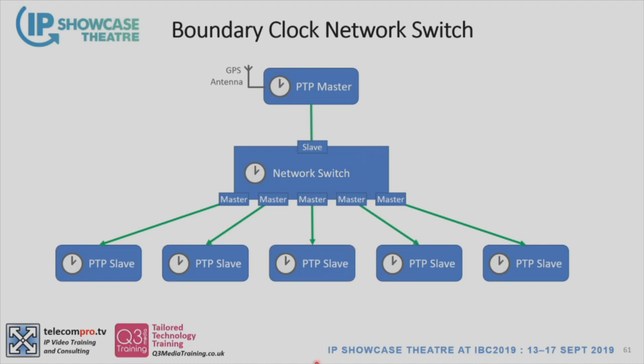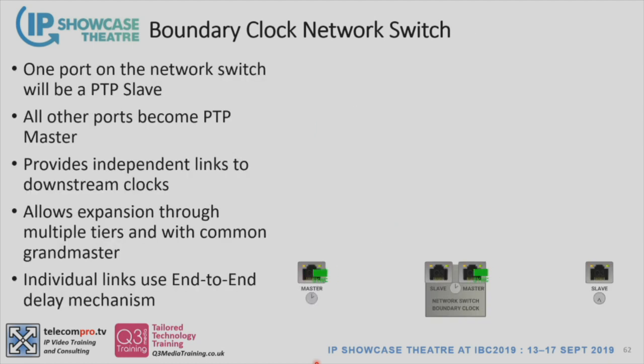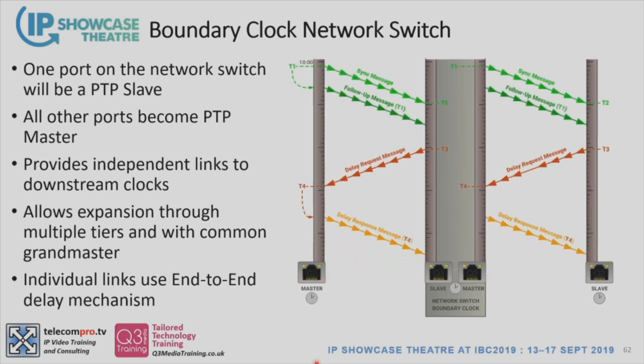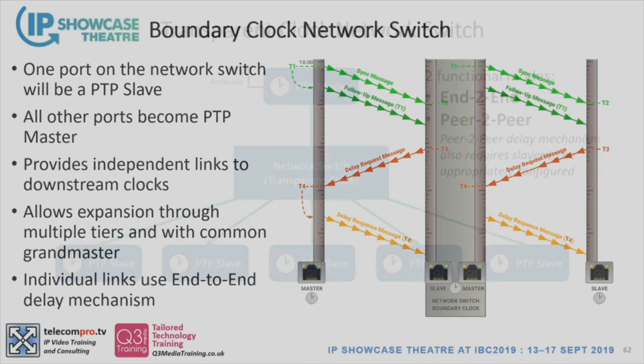Internally on the switch is some code, in either software or hardware, that's implementing PTP ordinary clock mechanisms on each of those ports. So how would that look? Drawing it, I've shown them very synchronous here. In reality, they probably wouldn't be quite so nicely aligned, but there are two independent discussions going on. There's the upstream discussion, synchronizing to the first master, and there are all the downstream discussions to all the myriad devices that might be other network switches and other boundary clocks, because this can be a big tree structure to distribute time, but it's all independent, again using that delay response mechanism.